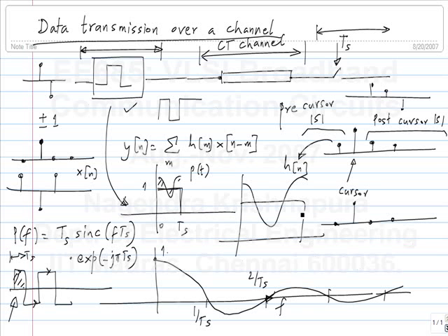So this, it turns out, has important implications on clock recovery, because the clock that you want has a frequency of fs, and that is precisely the frequency that is missing from the data. So you will have some difficulty recovering the clock from the data. Let's say the clock is not given to you. You are supposed to look at the data and then find out the clock. Now, from this Fourier transform, it looks like the clock frequency is precisely where the frequency content, the spectral energy, is minimum. Okay. So we'll see that part later.